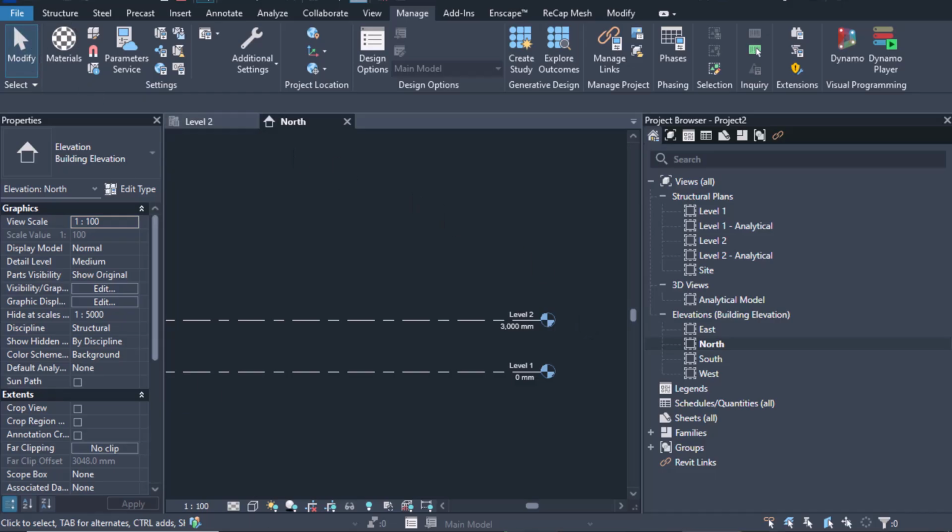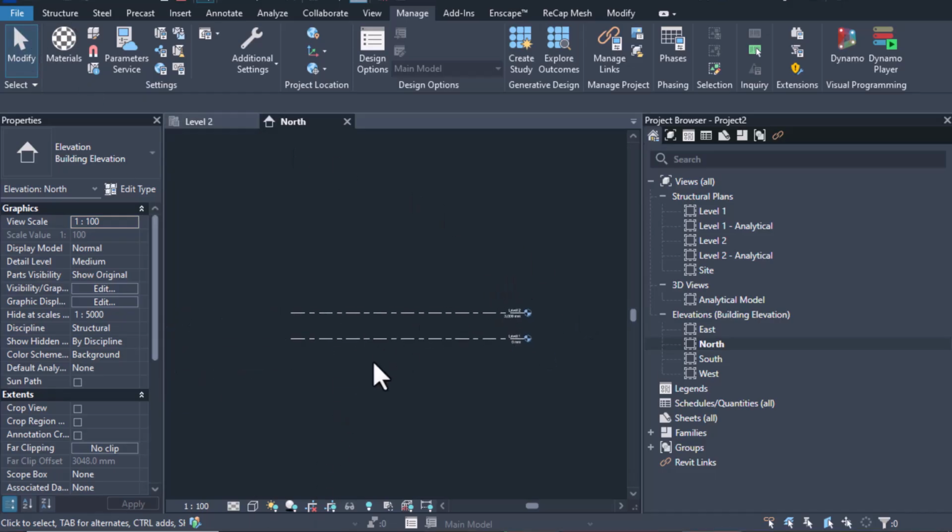So in order to start creating a level, first of all, you will need to know what the levels are and the different options to create them. In a project, the levels basically depict the structural heights, probably the story levels or the structural levels at which various floors are cast.